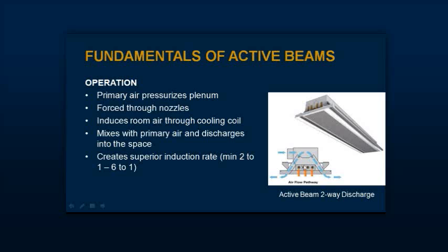Now, some of the things that was interesting in the way they put these products in is you notice that on the top right-hand side, that radiant panel actually has been cut out in such a way that it fits to that concrete structure, but still you get the overall grid pattern of layout that we had in the ceiling plan. Now, when this was selected, they also put in displacement ventilation as the media for providing ventilation air to the space and some cooling. They achieved a 44% energy savings compared to what their base model said it would be. And we helped them with the face selection, how we fit in the architecture, and so forth.